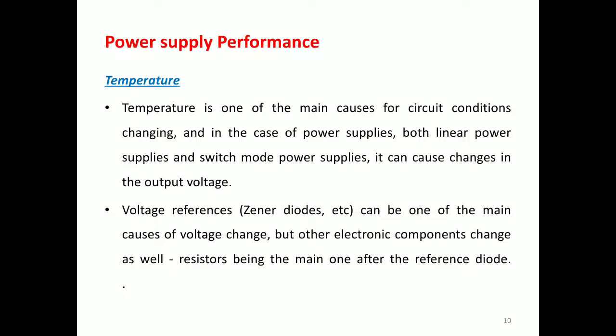Often various forms of temperature compensation can be added during the electronic circuit design stages of the power supply, and this will be considered to reduce any drift, but there will be some changes and this can be adjusted. This is a very important one. Even small changes can affect the circuit. So in this case, it is important to check the power supply temperature stability figures in the data sheet.